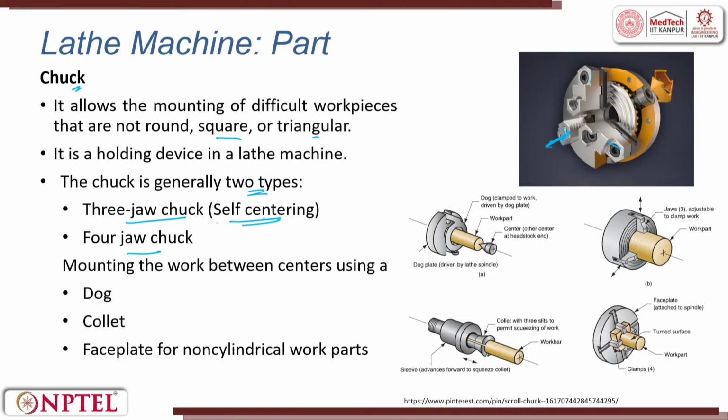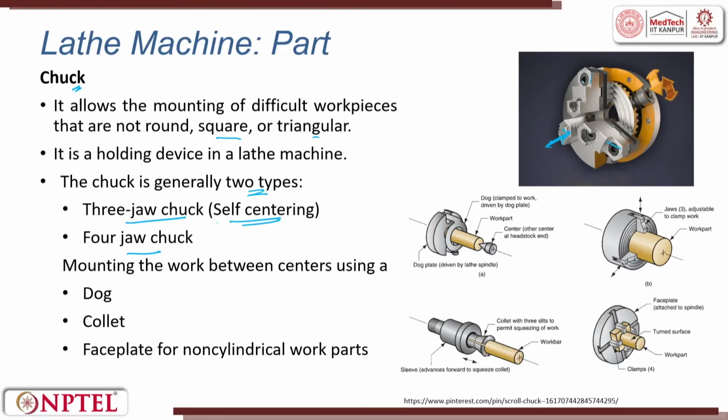3 jaw chuck is called self-centering because when you try to rotate one of the jaws, this rotates the basic gear where on the face there are teeth, right. So, when you rotate this, this rotates. When this rotates, it tries to rotate every jaw.